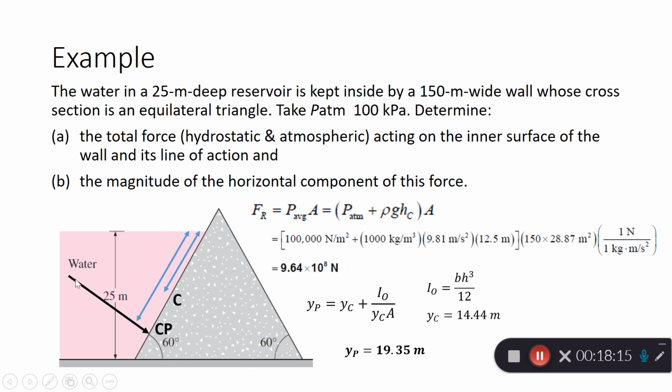You know that the force can be broken down into Fx and Fy. Horizontal component means you find the Fx component. Here you can work out the angle, and this angle should be 30 degrees. So the Fx component of the resultant force should be Fr cos 30.